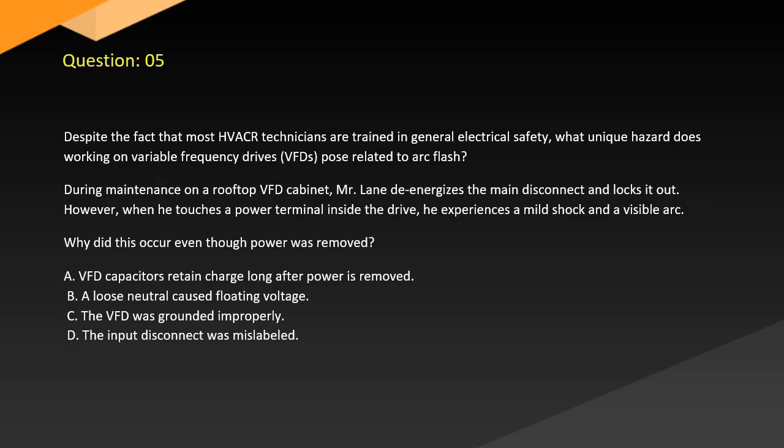Question 5. Despite the fact that most HVACR technicians are trained in general electrical safety, what unique hazard does working on variable frequency drives (VFDs) pose related to arc flash? During maintenance on a rooftop VFD cabinet, a technician de-energizes the main disconnect and locks it out. However, when he touches a power terminal inside the drive, he experiences a mild shock and a visible arc. Why did this occur even though power was removed?